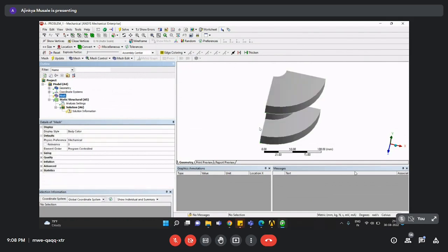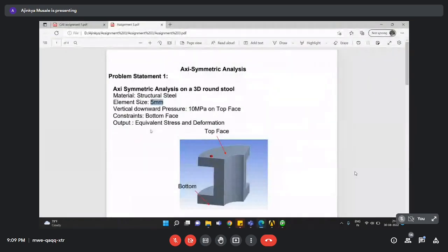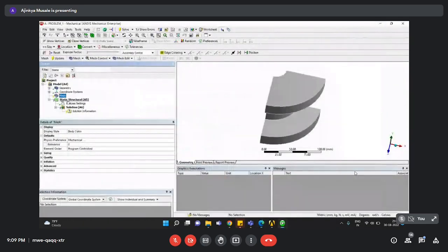So last time what I did, I simply right click on this mesh part and say generate mesh. But here what I want element size should be controlled one, and it is user defined one. So I should define what my element size is. So now in meshing, I have two categories. One is global mesh and second is local mesh. So just for time being, keep this in mind, global and local.